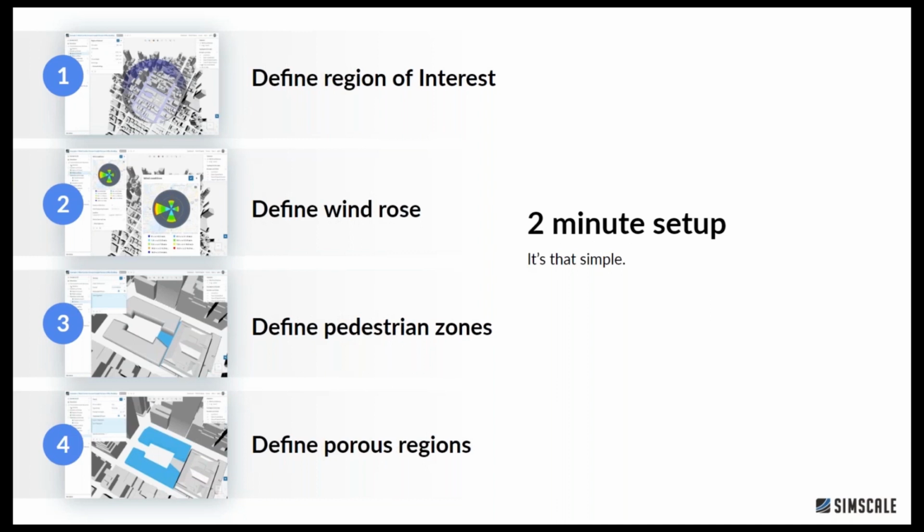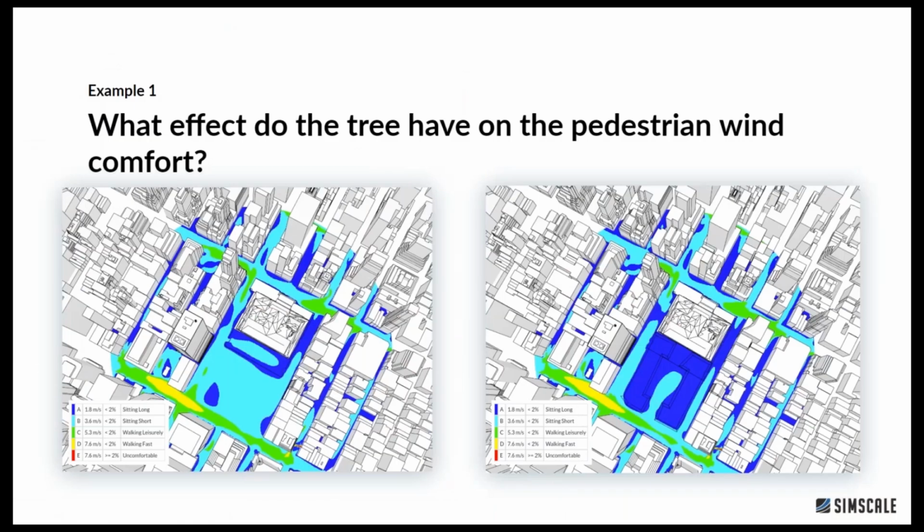So as I said, you select all the trees and you assign a type of tree, leaf area index and drag coefficient. What you will need to do as well is define the average height of these trees. This is an extra input you have to add onto this feature. Okay, so once we have this, we can have a look at the result.